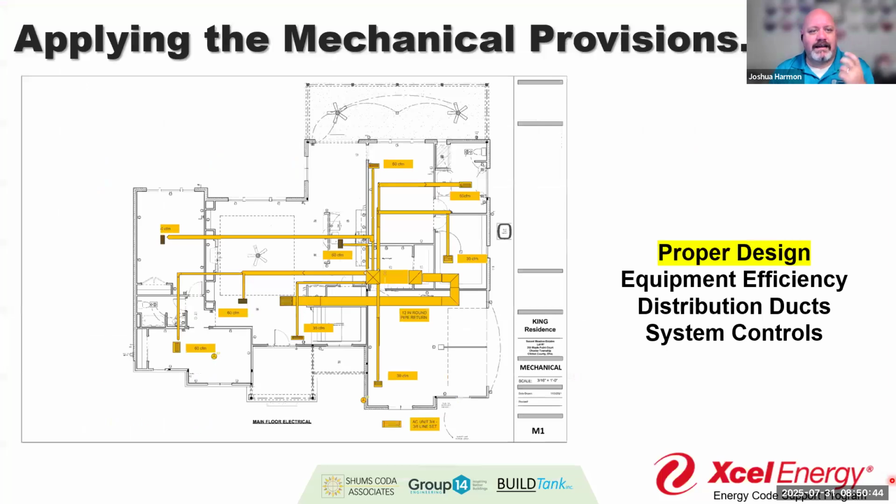Does that Manual J have the right and consistent insulation with what's going in the building plans? A lot of times, especially on longer, bigger projects, there's separation. The mechanical engineer and the architect are two different people. They sent me a REScheck, and then they didn't tell me we changed some things. So this wall no longer does what it's supposed to, and I'm going to have the wrong sized equipment going into the building.